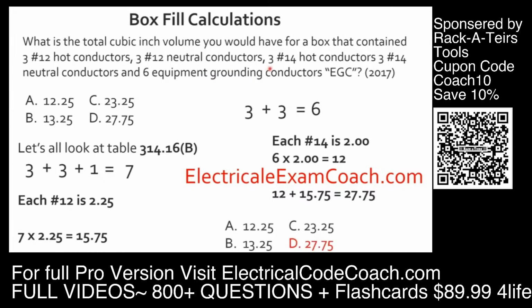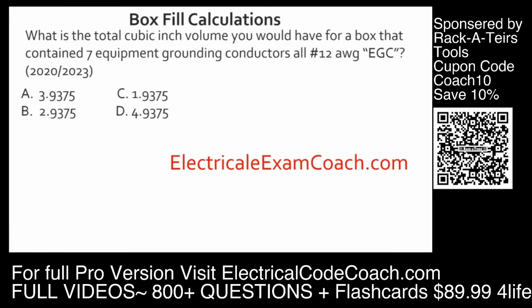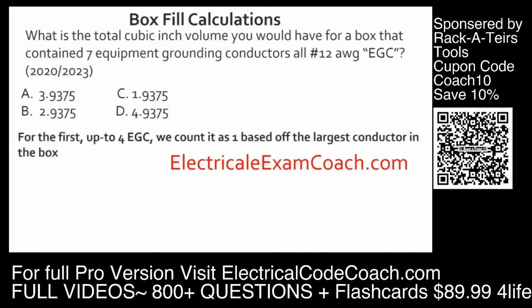Now let's move on to the 2020 and the 2023. What is the total cubic inch volume you would have for a box that contained 7 equipment grounding conductors, all of the 12-gauge persuasion in the 2020 and the 2023? I left out all other conductors because you're going to use the same rules in that after you do this calculation, you group it with whatever the largest conductor is in the box, like you learned previously. What we're going to do is count the first 4 and count it as 1. And then a 1/4 inch increase for each one past 4. Sounds complicated. We're going to break it down very simply.